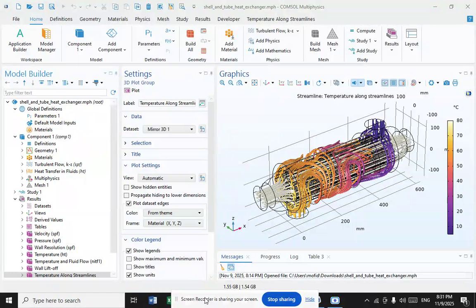However, it is more likely for the heat exchanger to foul faster, and a small size makes mechanical cleaning of the fouling difficult. To prevail over the fouling and cleaning problems, larger tube diameters can be used. Thus, to determine the tube diameter, the available space, cost, and fouling nature of the fluids must be considered. And what about the tube thickness?